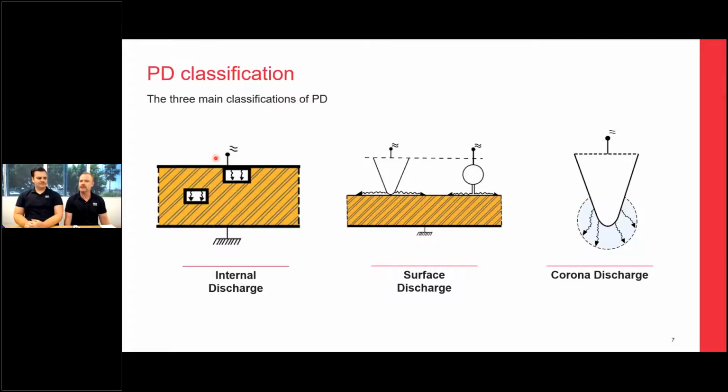But a lot of that buzzing and arcing will be coming from sharp points just due to the physical construction of your assets, and it's discharging from that point into a gas. When it's in an outdoor switchyard, it's generally not a problem because there's airflow at that point, blowing away all the chemical reaction that's occurring.